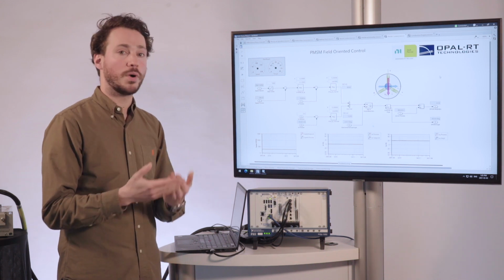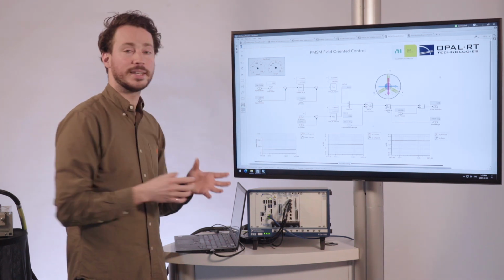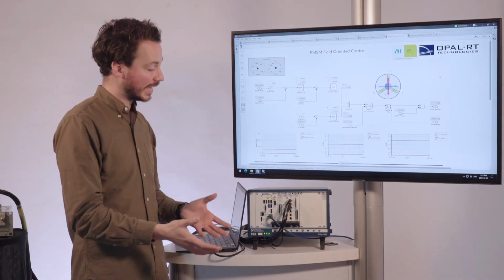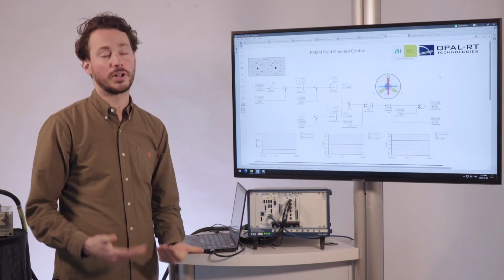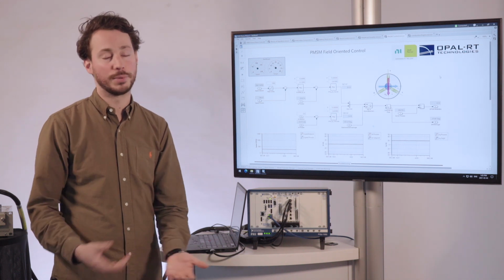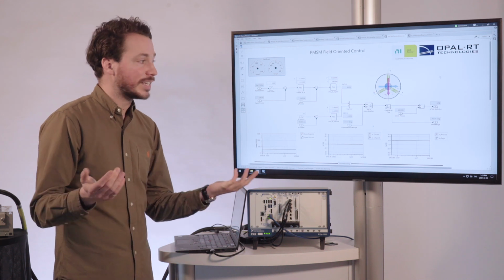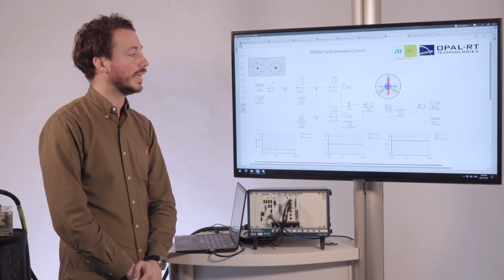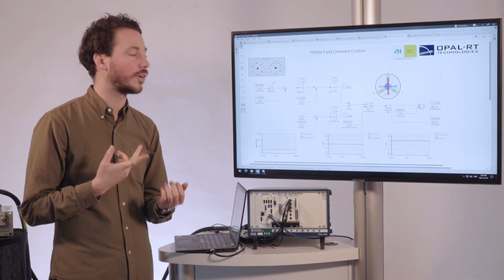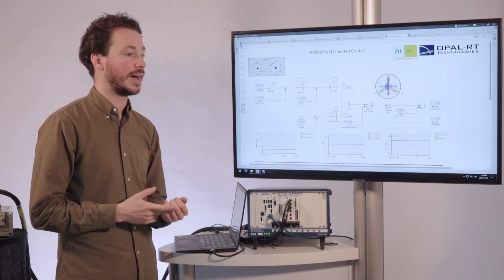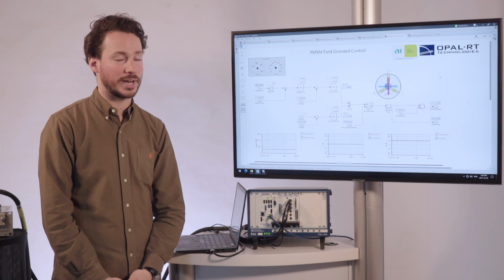But if ever, for example, you want to be able to test your FOC as an external hardware in the loop, it's just a matter of taking this, implanting it, let's say, on your ECU, and then connecting it to the various I/O of the FPGA module. And that's how you can perform a real hardware in the loop with the gate driver or with the motor controller for the drive unit. Okay? If you want to do sensor or sensorless, all of these are possible. Inside of the add-on that I was mentioning before, we do support resolvers, encoders, Hall effect sensors, and we can also have custom sensors inside the FPGA, so to be able to have all control strategies taken care of.